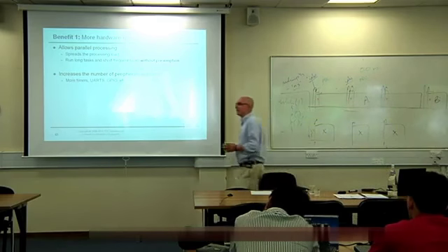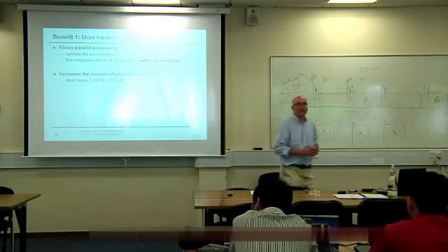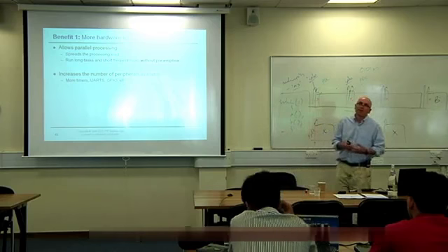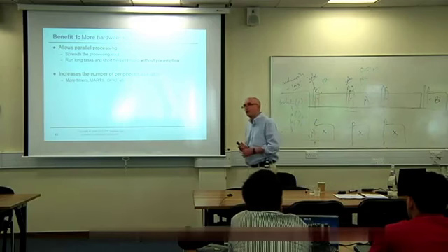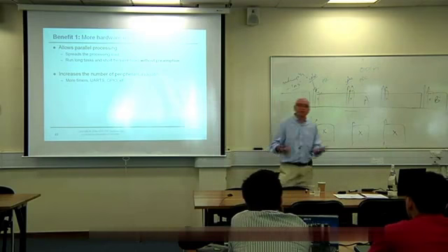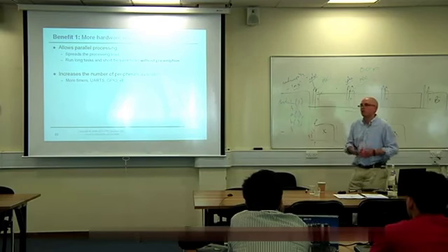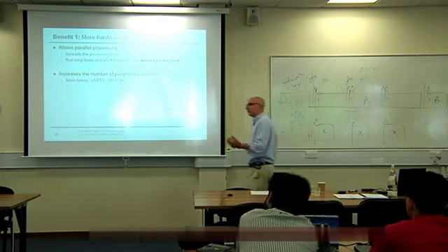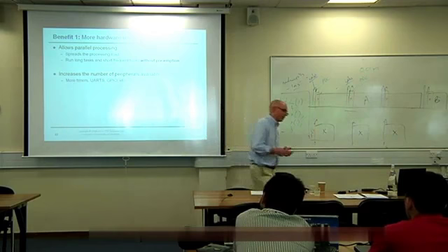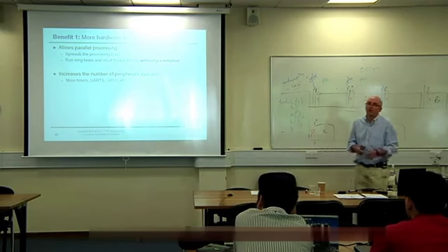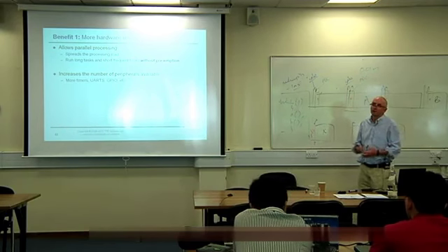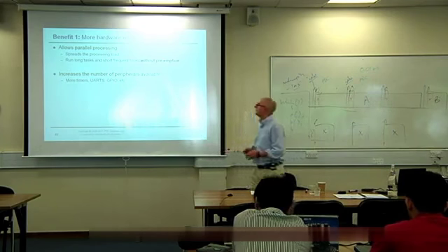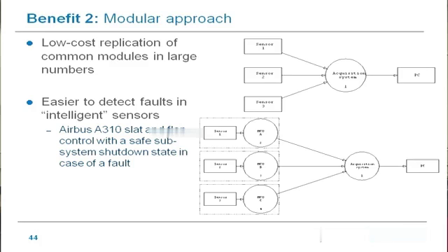Compilers are expensive. Tool sets are expensive. Most of the time, you might work in application areas that only require a comparatively limited peripheral set. Suppose your 8051 only has one UART and you need two UARTs. Why not use two 8051s? Hook them together. Synchronize those two processors, do data transfers between them. You can use the same set of tools, and you can make the system work quite happily in that form. It might even give you increased reliability. Talk about some of those things. You might have some greater immunity to errors, etc.